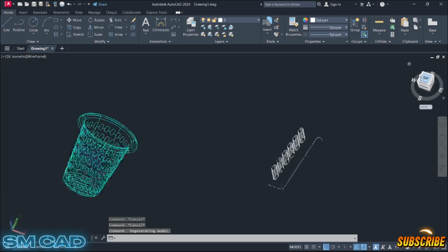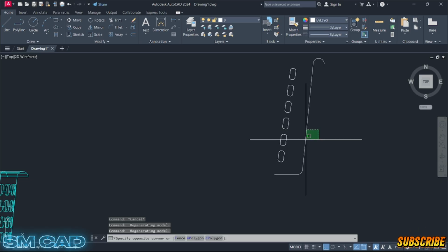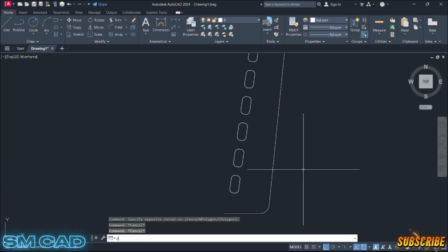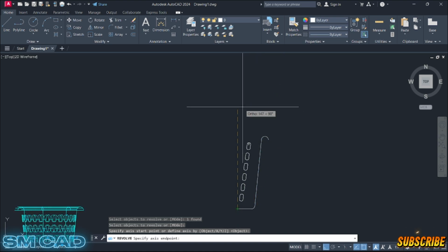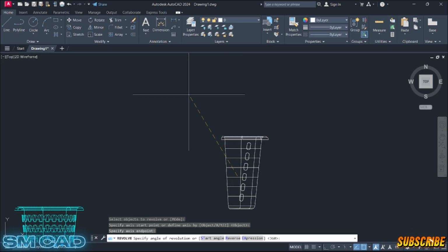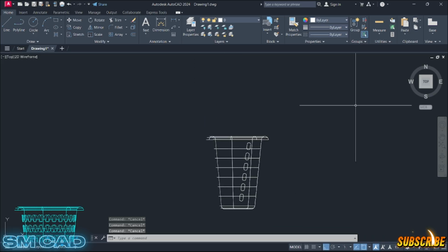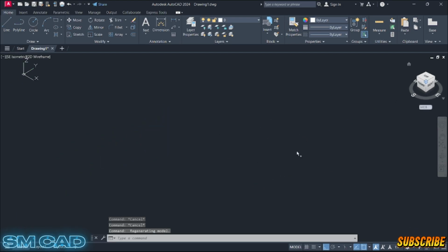Now I will revolve this section. So we have command revolve. We will select this, enter. This is the first point, second point, and 360 degree. Okay. Now we will see here.